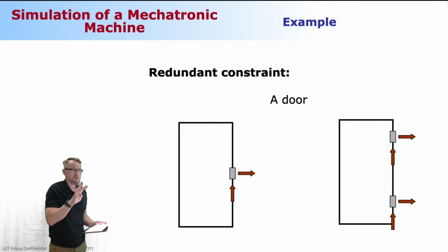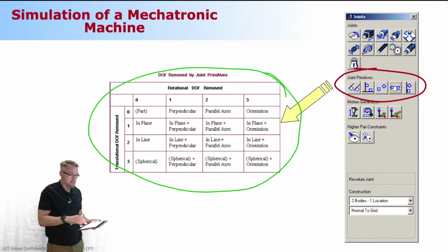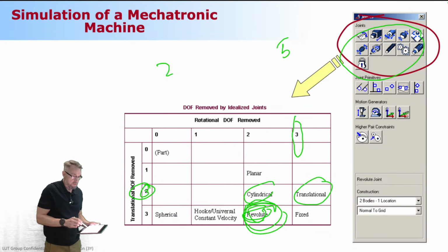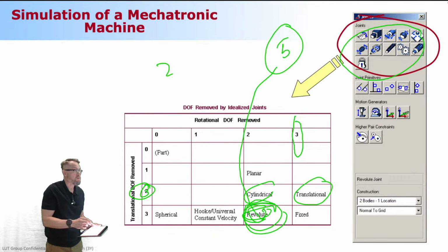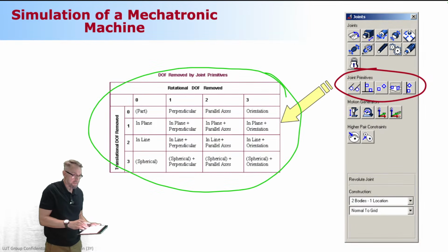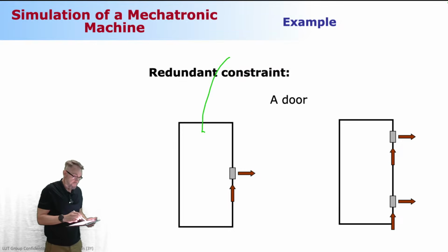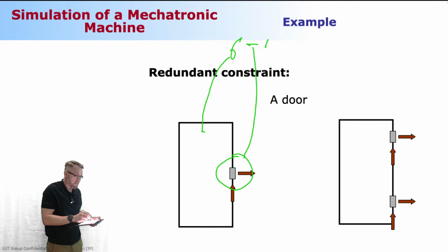Now comes something quite surprising. Let's take a look at the door at the back of this lecture room and see how many degrees of freedom we're going to have in our door. We're going to constrain the door to ground using a revolute joint. Again, you need 5 constraint equations. Assuming this door is in a spatial, 3-dimensional case, it needs 6 generalized coordinates. With one revolute joint, it's going to be 6 minus 5, so 1 degree of freedom.